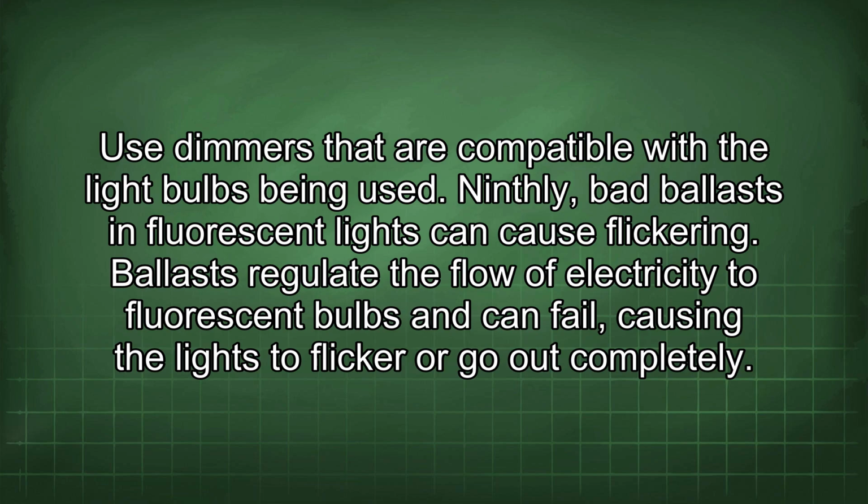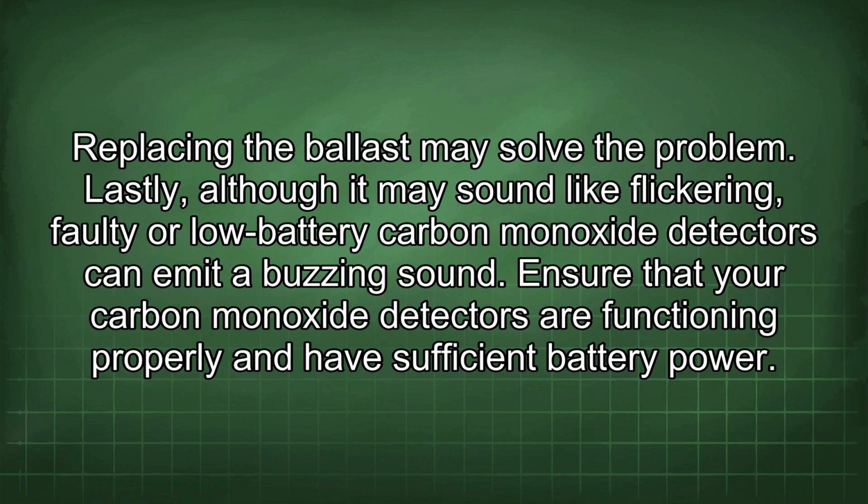Ninthly, bad ballasts in fluorescent lights can cause flickering. Ballasts regulate the flow of electricity to fluorescent bulbs and can fail, causing the lights to flicker or go out completely. Replacing the ballast may solve the problem.